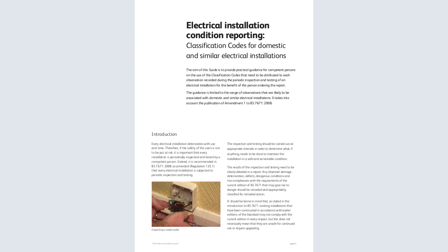So the moment you achieve that certificate, you go there, and the first question that will be asked is about the inspection, the installation inspection test. What are the major tests that are done on site? How do we do it? You remember I gave you a video of how we can do all these things: how the loop impedance test is done, how the insulation test is done.